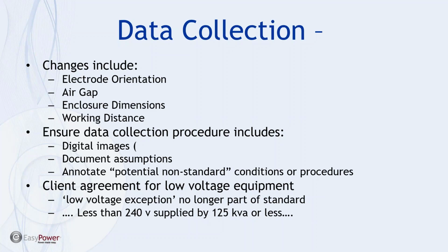Now, obviously, if the equipment's hot, you very well can't necessarily measure the air gap or even the enclosure dimension safely. So this takes a little bit of forethought, but above everything else, document any assumptions you make, especially if the equipment's energized. And in some regards, that's probably the primary reason for selecting the default values. Likewise, make sure you annotate any potential non-standard conditions or procedures.